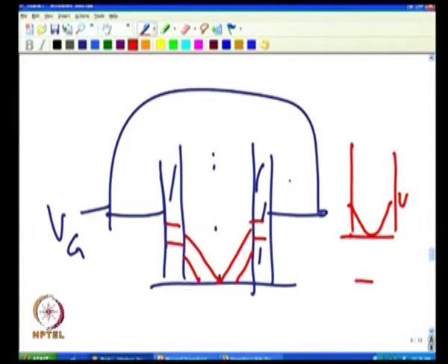After that, if I increase beyond that point, you see the difference is not there. Then afterwards, it keeps on moving up like this till I get twice phi F. That is a double gate MOSFET, symmetric. So, people are looking into devices which are actually realized like this. Both gates are connected together, so that one gate controls, because after all you do not want to have one supply for the front gate and one supply for the back gate. Make it symmetric, connected together. There are some issues that we will see when we sort them out by some other methods. Okay.